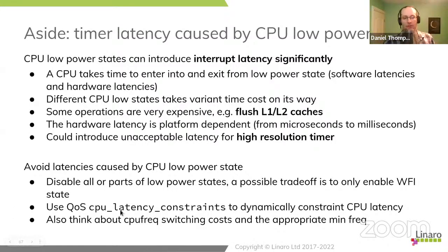So if you have one of these modal systems, you can use latency constraints. Entry and exit times into low power states are usually described, in an ARM system, in the device tree if it is an embedded system. And you can basically say, I do not want to go into these modes if it's going to cost me more than this amount of time, and then those low power states will be disabled. But they can be raised and lowered dynamically as needed.